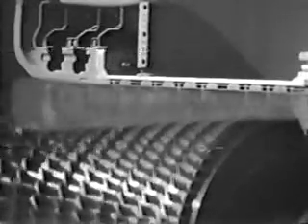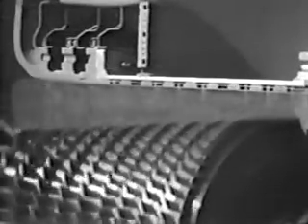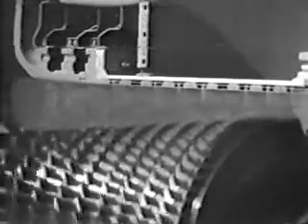Let's look very closely at the space between one set of rotors and stators. Here, the shape of the air path is decreasing. In fact, we have a miniature nozzle. This causes the velocity to rise slightly before the air enters the next set of blades. So the nozzle effect is the second way that air velocity is maintained. As the air moves between hundreds of blades on 11 stages, its pressure is multiplied by diffusion and its velocity rises and falls in the process.